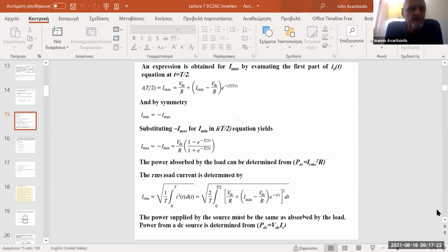And when you come to the calculation of RMS values, you must remember what the definition is, and how we can do that by applying the definition. In other words, we take the square root of the integral over the period of the time varying quantity, in this case i(t), of the square of this time varying quantity, as it is shown at the bottom.